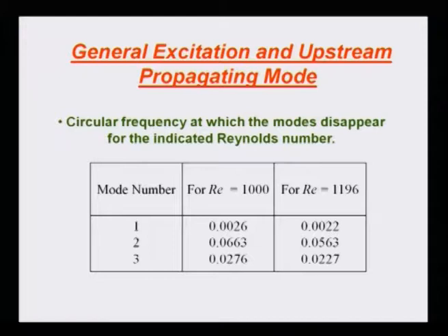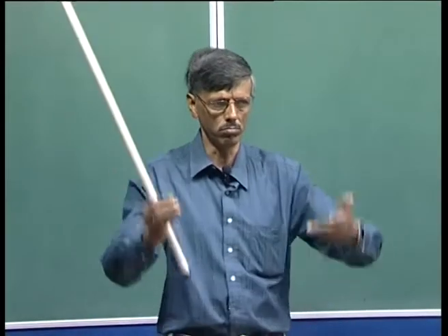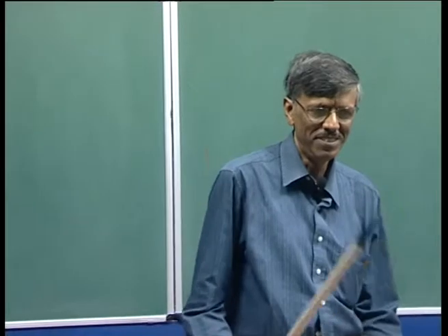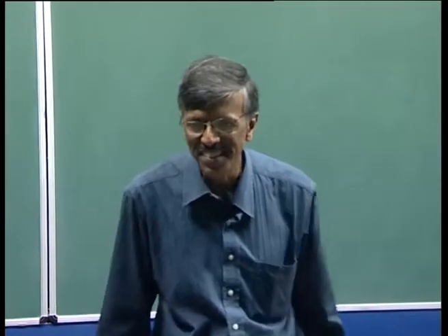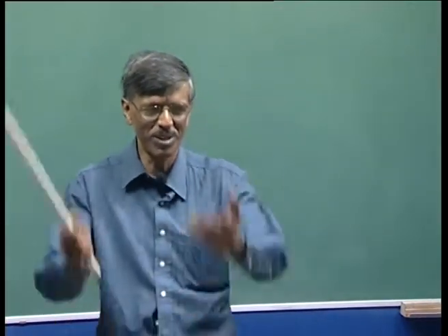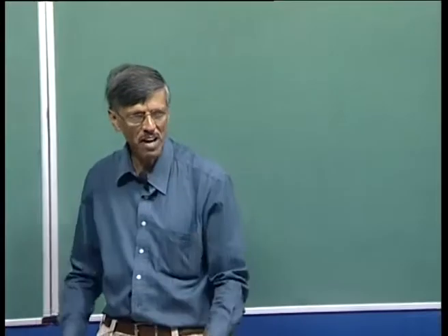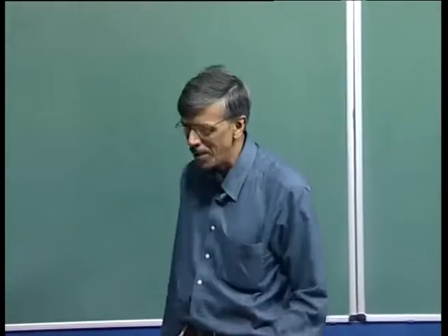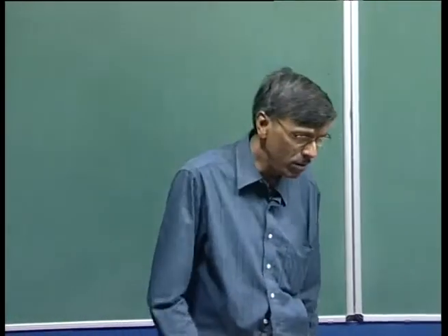The strange thing that appeared was this: once again people did not see any wave per se, but what they saw was that the whole shear layer went up and down, as if the boundary layer is breathing. That's why these are called breathing modes. So as if the whole boundary layer is heaving up and down.